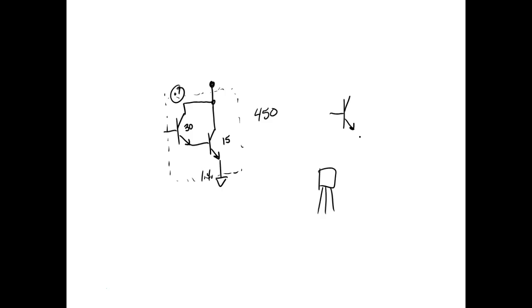So what did I do? I changed it out, and the printer did the same thing. Well, then I got smart and I looked up the part number and found out it was actually a Darlington transistor. And then everything made sense. I was going by the schematics, and when they drew the schematics, they drew it as a single transistor. So don't take for granted schematics are always correct.